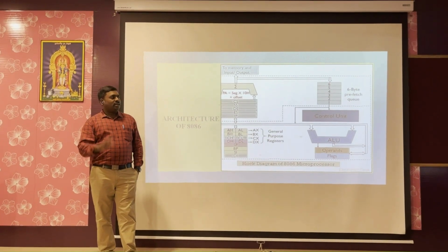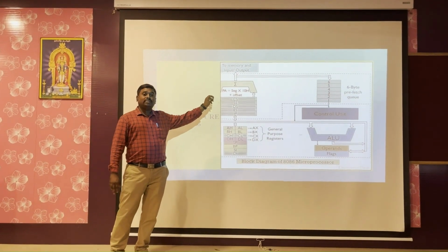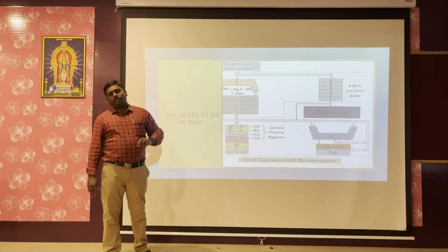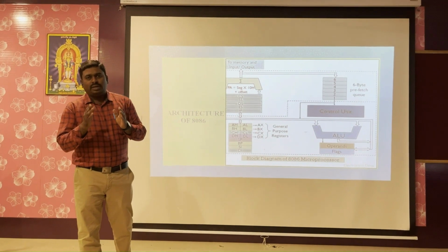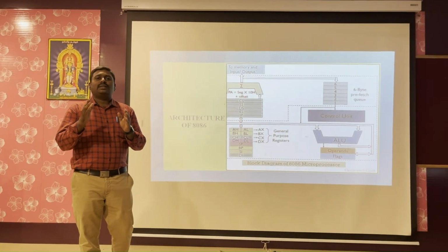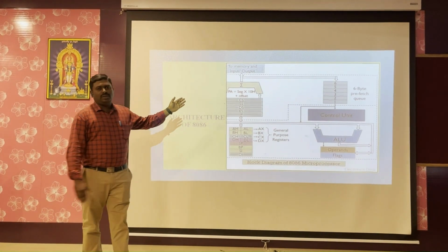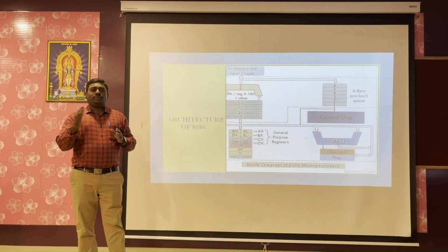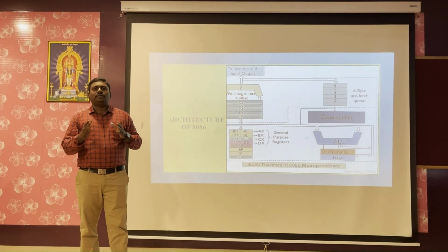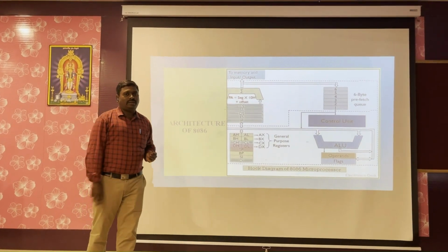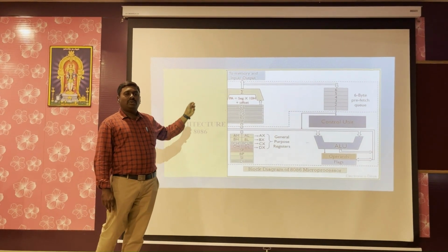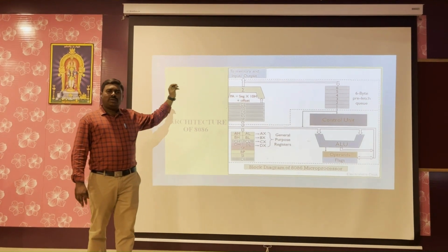Each physical address is a combination of a segment address plus an offset address. Each segment address is multiplied by the hexadecimal value 10H and added with the offset address. By calculating this, we get a physical address, which is nothing but an effective address. This address helps to locate the data for the other devices.